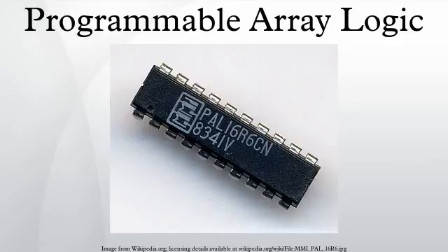Programming languages. Though some engineers programmed PAL devices by manually editing files containing the binary fuse pattern data, most opted to design their logic using a hardware description language such as Data I/O's ABEL, Logical Devices' CUPL, or MMI's PALASM. These were computer-assisted design programs which translated the designer's logic equations into binary fuse map files used to program each